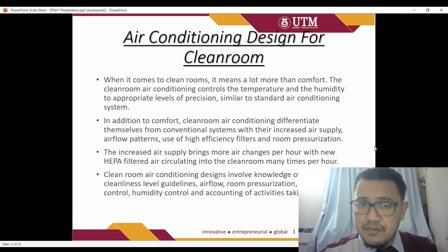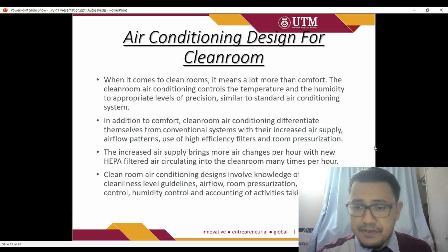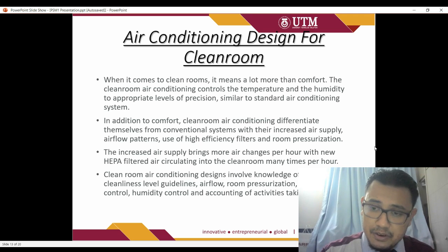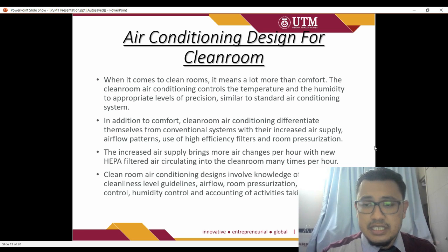Then in addition to comfort, clean room air conditioning differentiates itself from other conventional systems with its increased air supply, which introduces fresh air for pressurization, for infiltration, and to replenish the exhaust taken out of the clean room area by the machines. This increased air supply brings more air changes.